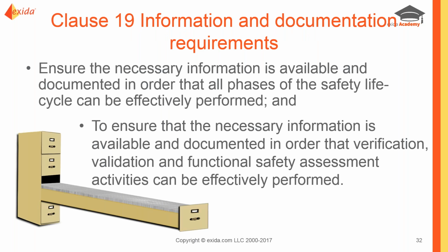Clause 19 addresses what are the documentation requirements. And certainly the reason we're doing this documentation is to make sure that the appropriate information is available, that it's well documented, so that what we have in our safety instrumented system is what we intended in order to mitigate the risk. And a big part of communication through any project is that documentation.